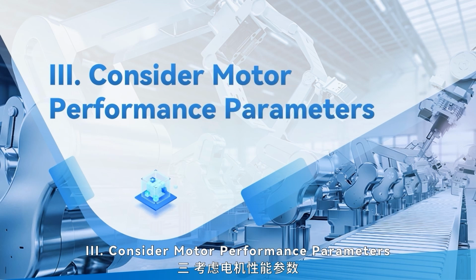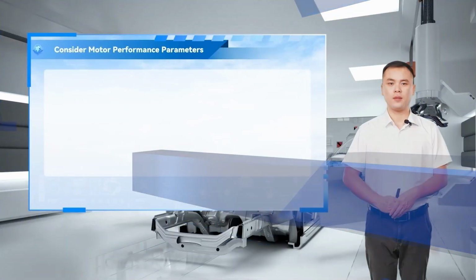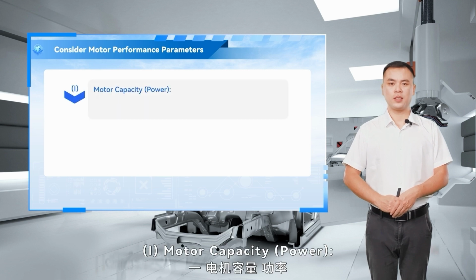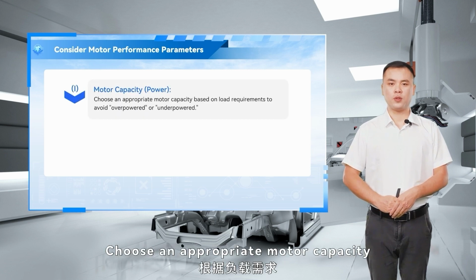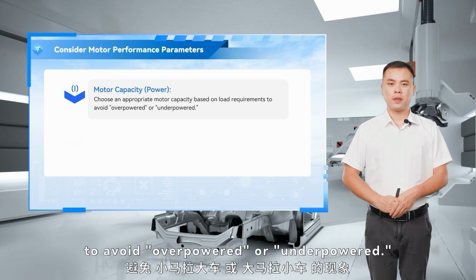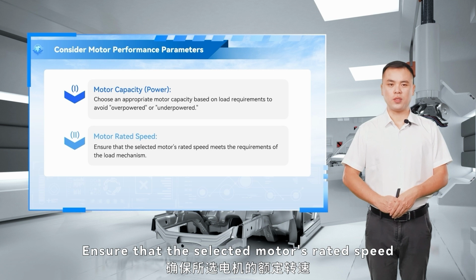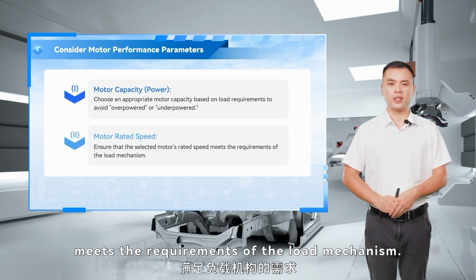3. Consider motor performance parameters. 1. Motor capacity. Choose an appropriate motor capacity based on load requirements to avoid overpowered or underpowered. 2. Motor rated speed. Ensure that the selected motor's rated speed meets the requirements of the load mechanism.